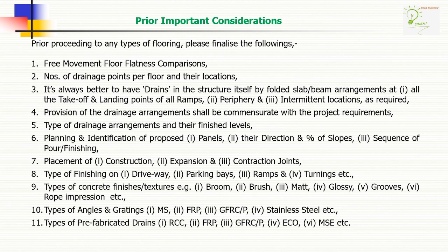Provision of the drainage arrangements shall be commensurate with the project requirements. Type of drainage arrangements and their finished level. Planning and identification of proposed panels, their directions and percentage of slopes, sequence of pour, finishing, etc.